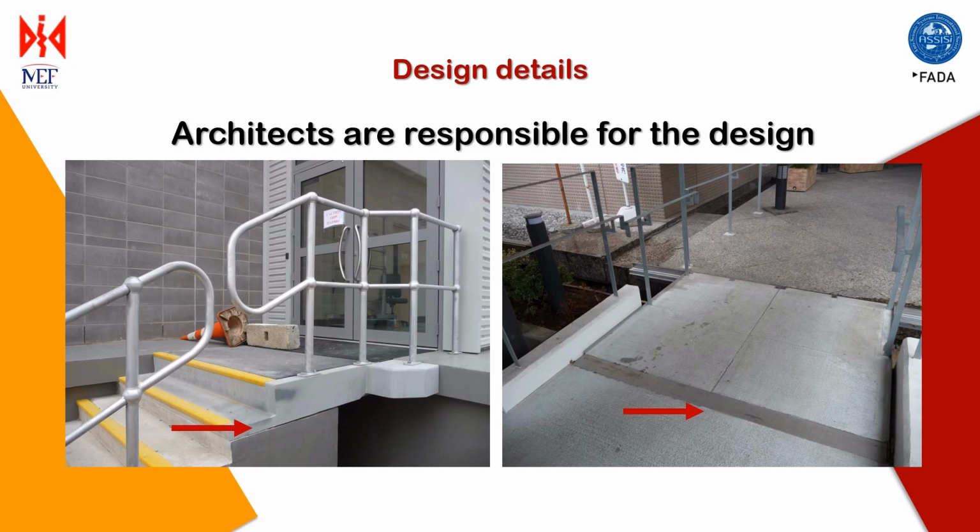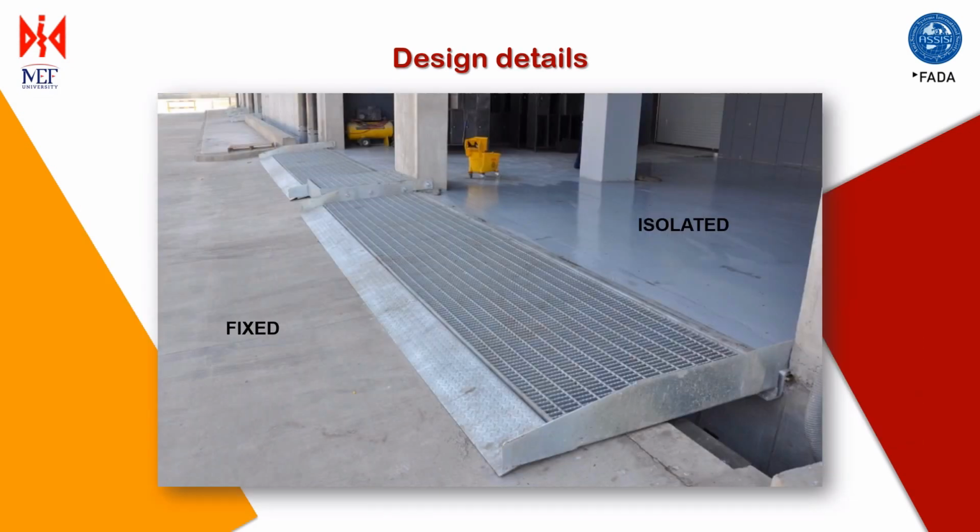A precast moat cover where movement parallel to the entrance is accommodated by the angle sliding joint. Movement at right angles occurs when the precast slabs slide along the steel support rails that are attached to the isolated structure. This is in Tokyo.